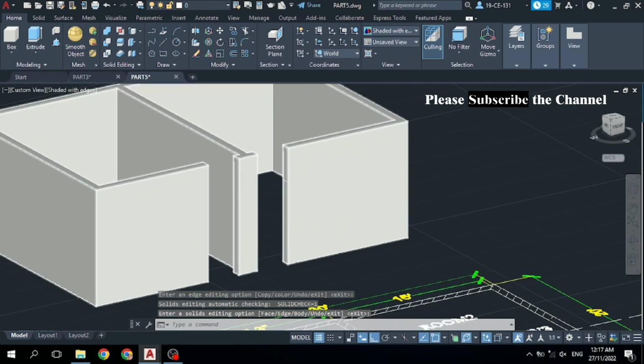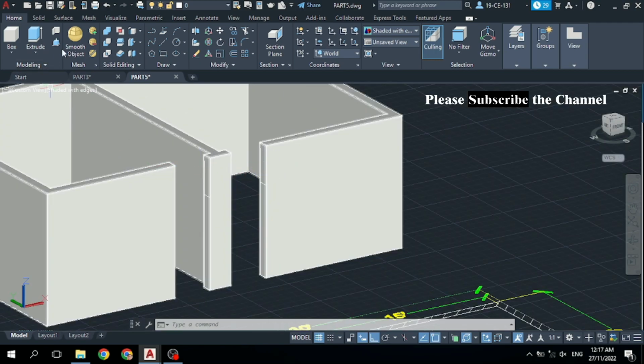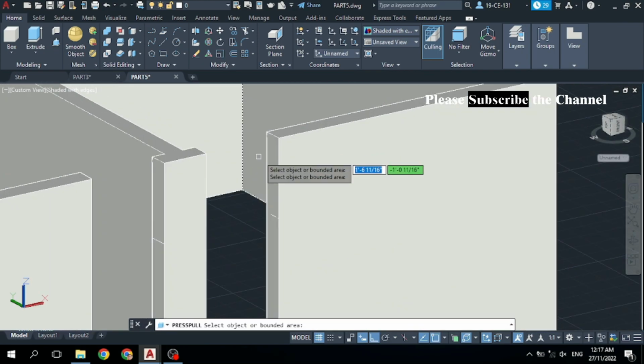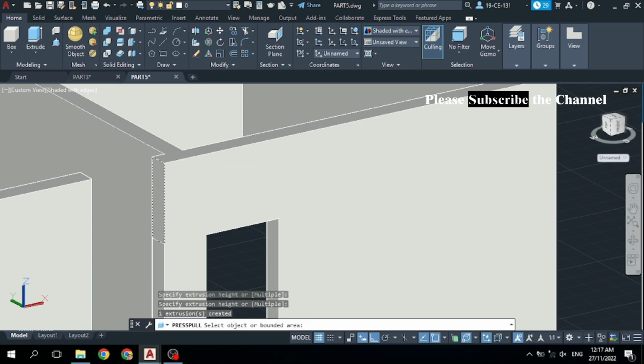Now you can see this edge line is copied here and here, and after that take the press pull command. You can see this press pull command and click on this edge and come to this side and click at this corner, and after that select this space and come to this corner and click here.